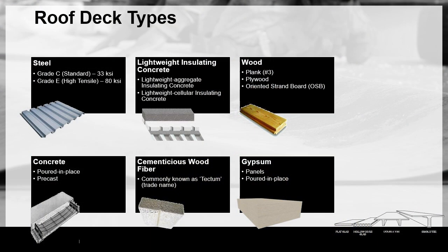Okay, so let's go to our second learning objective, which is understanding the types of low slope roofing products. We're going to start with the bread of the roof, the deck types. So Rob, can you talk about the different types of roof decks out there? Sure. There's multiple types of roof decks, and I'll start with the most common and go to the least common. Most common would be your steel deck. If you look up inside of a building and you see metal that looks kind of like a W almost repeating itself, that's a metal deck. Typically the type is a B deck, but basically it's steel, and they lay it out in long sheets, 22 gauge thick, and that's your most common deck. Second most common, I would say, would be wood. Typically plywood would be that structure, solid, cheap for buildings, works out very well.